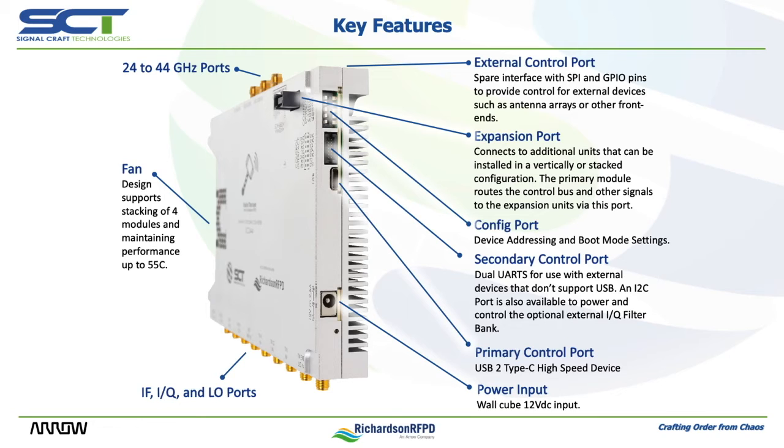Control of the module is provided via USB or SPI interfaces. Most users will interact via console over USB. Alternatively, embedded controllers may access the UART or SPI buses available on the secondary control port.